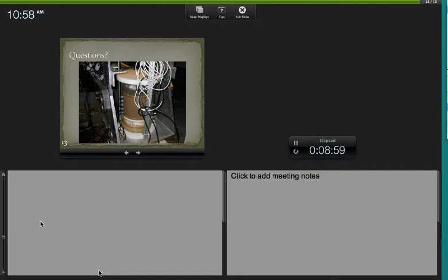Right. The sample, we actually ran this test 4 times. I chose the data from the best test. We spun for about 2 days on this one, and it still wasn't fully drained. As I was talking about, the silt takes a very long time to drain because of the grain size and the compaction level that you choose.